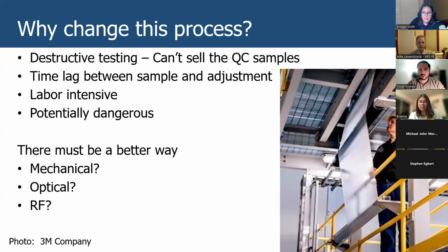Not too thick, not too thin. And everything is great until there's a change. Like you run out of the batch of adhesive and you introduce a new batch of adhesive which might have slightly different properties. The density might be slightly different. Or you run out of a batch of backing material.